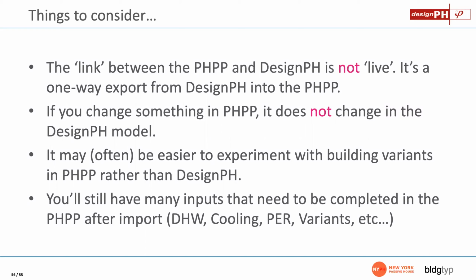It's a one-way export from DesignPH into the PHPP. If I change something in the PHPP, it does not change back in the DesignPH model. And similarly, just because I change something in the DesignPH, until I export it out to the PHPP, it doesn't change. It's not in any way a live link. It's not really connected. It's just an export from DesignPH into the PHPP.